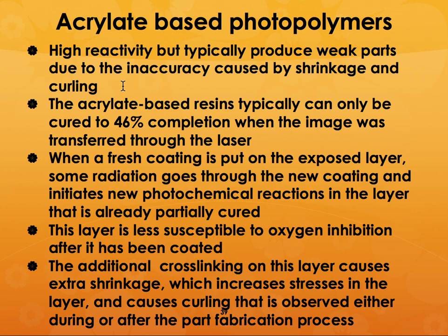I'm sorry, there is a lot of writing here, but what you're doing is you're essentially curing each layer, and once the laser beam hits the resin, it also partially cures more the layer that is directly beneath the layer that is being cured. So that is going to give you some kind of shrinkage as well as heat generation and things like that.